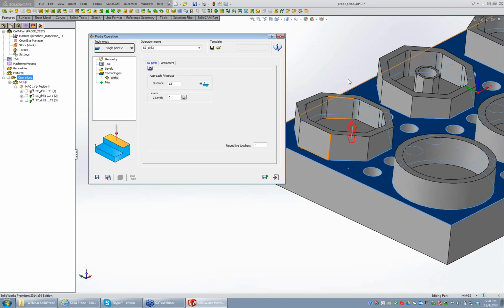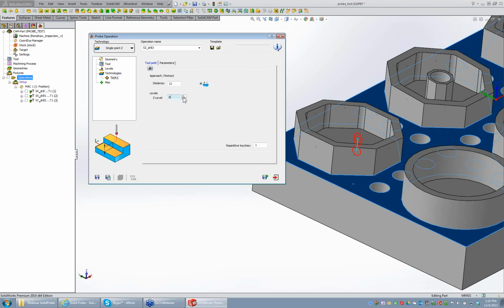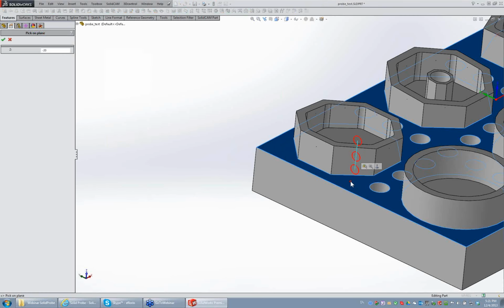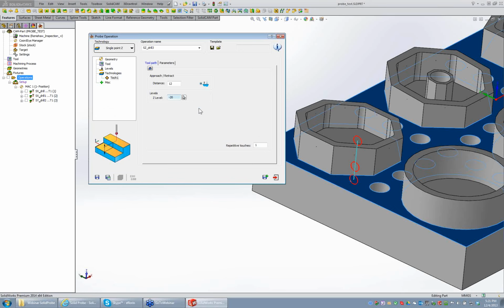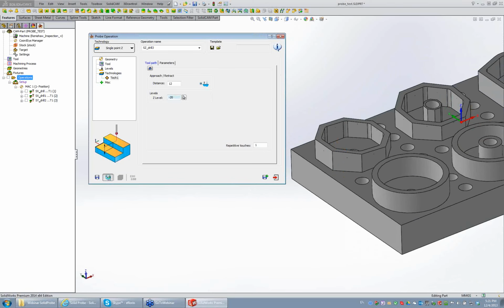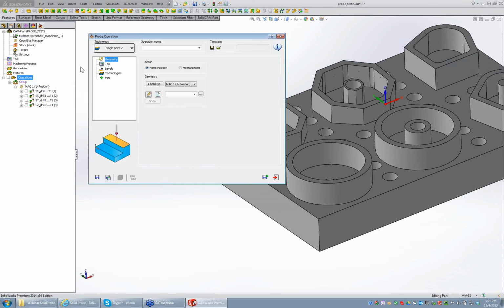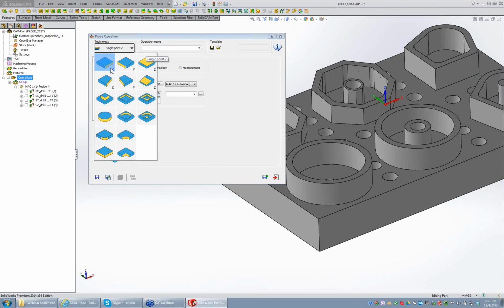It can be done only in the tool axis. Now, the level: I can go manually to the selected level or copy it from the part. Touch the level and we have -20. This is about single point measurement cycles.